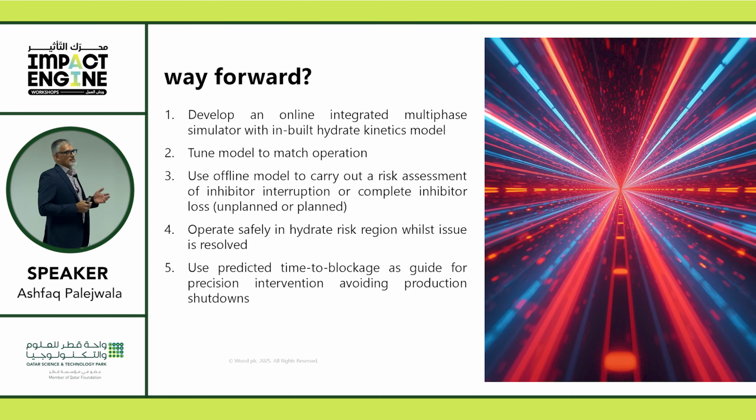And really, the answer to that is that if you can develop an online integrated multi-phase simulator, which I'll say can be done, has been done, is being done, and if you can tune the model to match operation, you can use an offline model to carry out a risk assessment to see if I were to lose, say, a MEG pump on a very cold day or a very cold night, would it really be a problem or not? Can I live with it, or do I need to take major action?